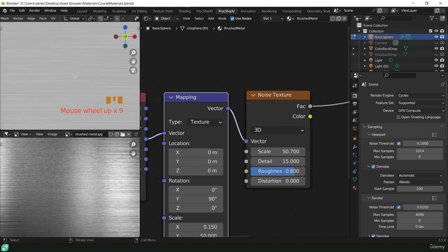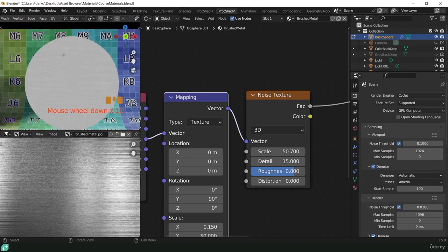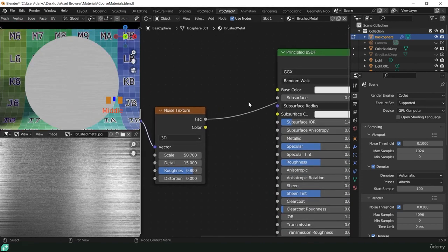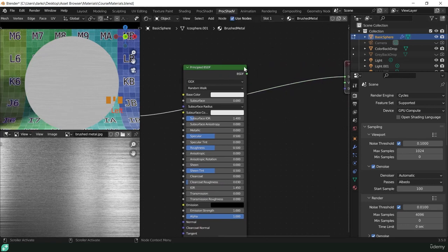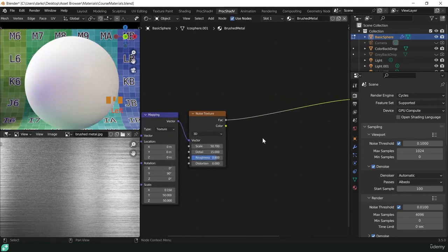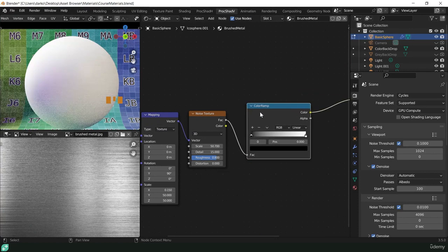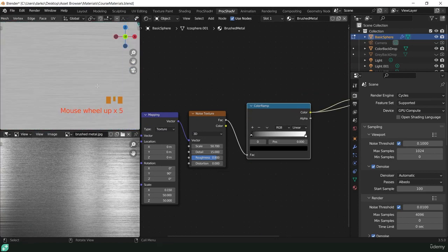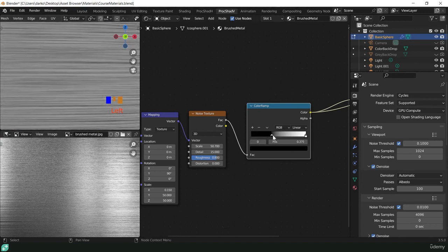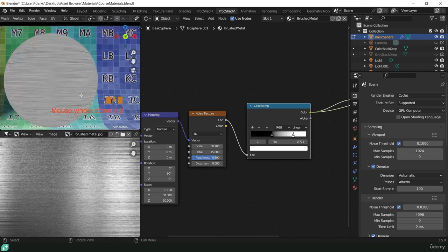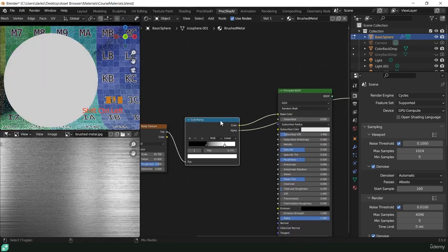Now, it's probably not quite apparent on the recording, but there's not much contrast on this. It might just be showing up as a flat grey on your screen. I hope not. So let's increase the contrast on this by adding a colour ramp node. So this is a node that we should be quite familiar with by now. We can take up our black values, make that a little bit more contrasty, and we can take down our white values as well. And it just gives us a lot more contrast on our texture.